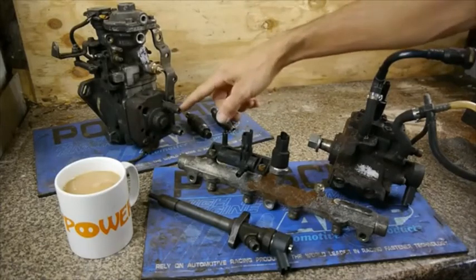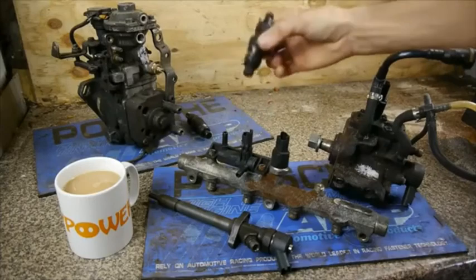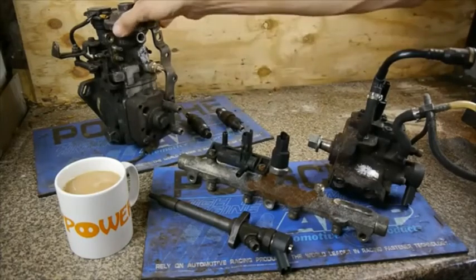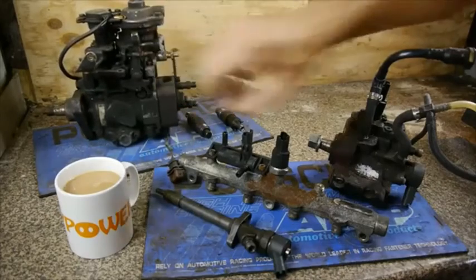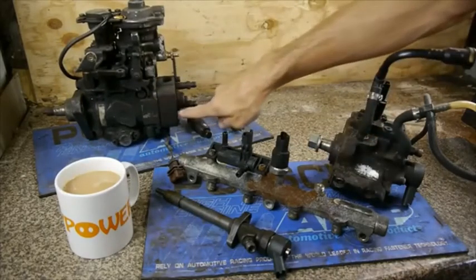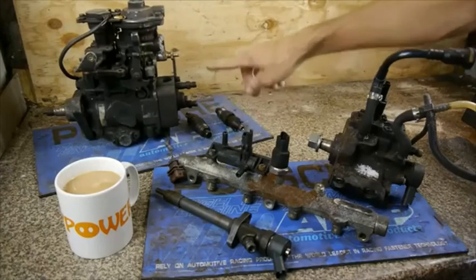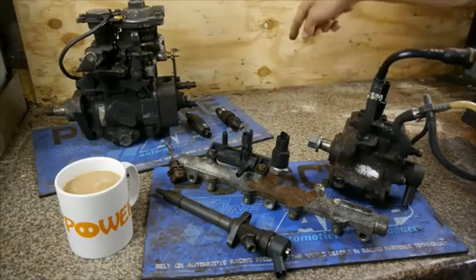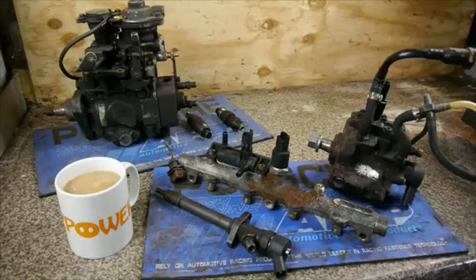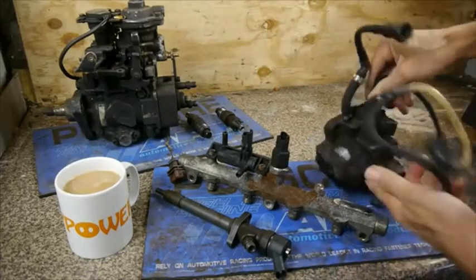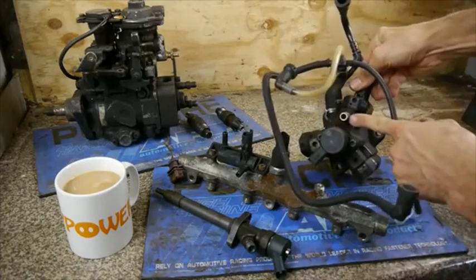And each of these delivery valves runs via a pipe to one of the injectors. As the shaft inside rotates, not only do the vanes inside create the pressure it requires, but they also deliver fuel via the head, via a shaft in here, to each valve as it rotates, and then each one goes to each cylinder and creates the firing order. As opposed to our direct injection here, which simply has basically just one output.